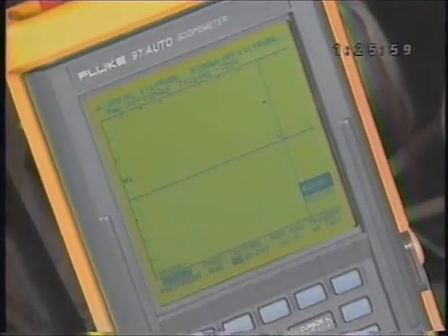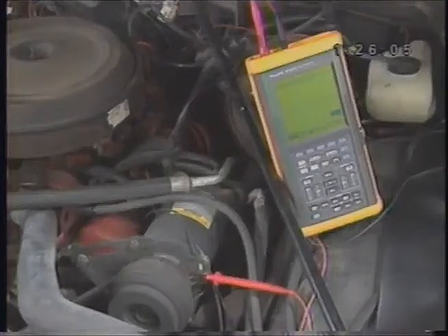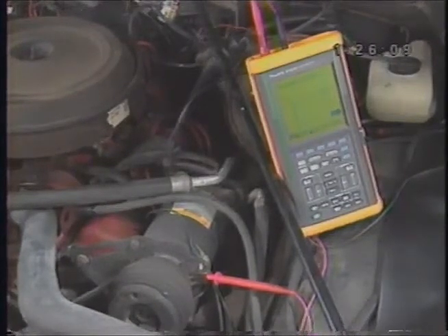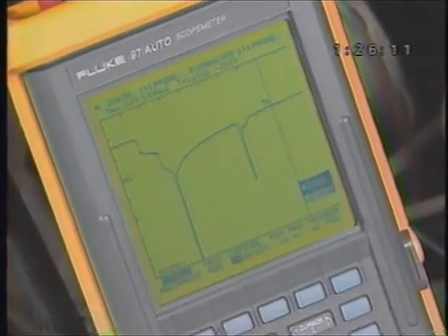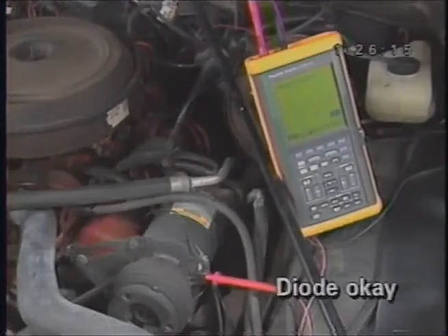Since the voltage hasn't dropped below negative 20 volts, Scopemeter shouldn't display a waveform yet. Now turn the air conditioner off. If the clamping diode is bad or isn't there, a voltage spike occurs. If the diode's okay, you won't see a waveform displayed.